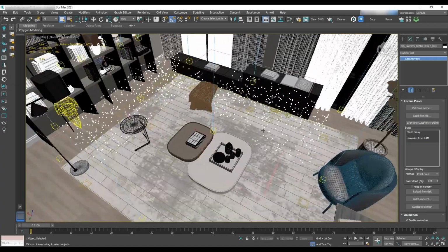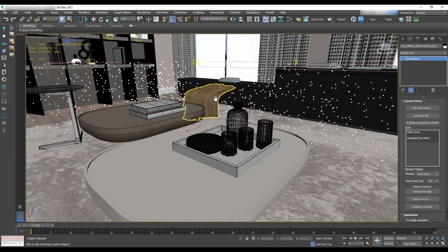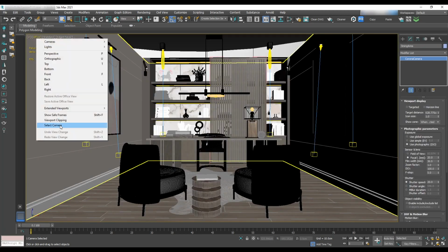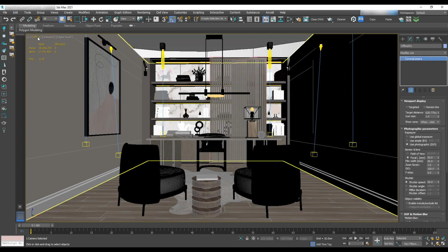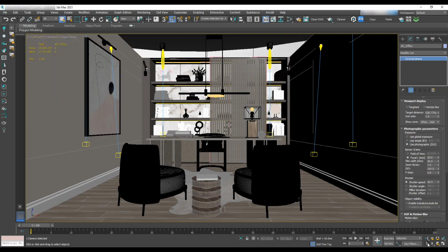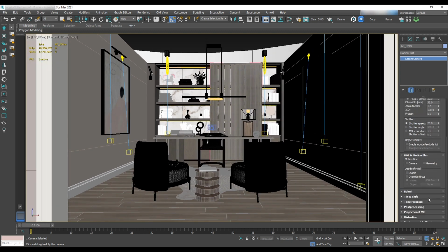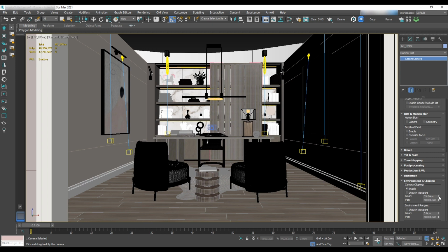To do that, select the still cam for each area that we made and make a copy of it. We'll start off with Office Cam. Go to the camera, select Camera, Ctrl V, and then select the camera and rename it to AC_Office. With the dolly camera, move back. In Environment and Clipping, remove casing from the view by slightly adjusting the number.